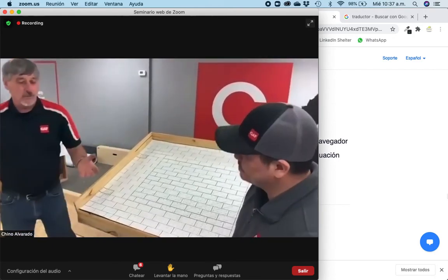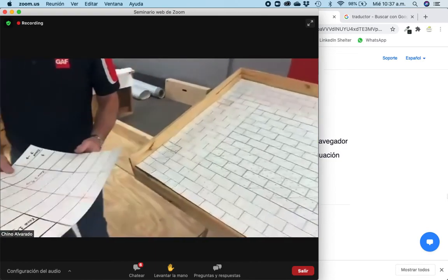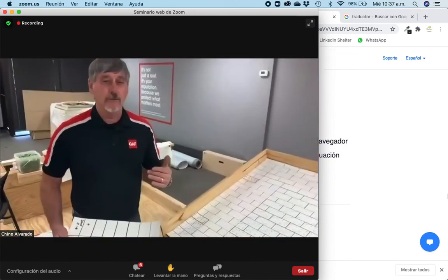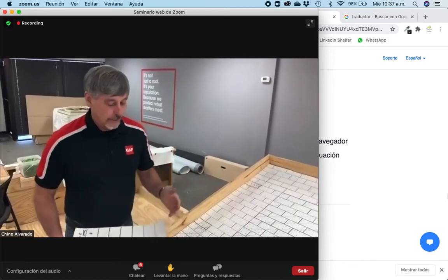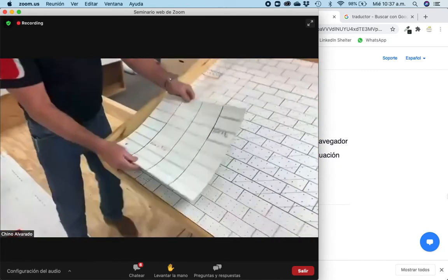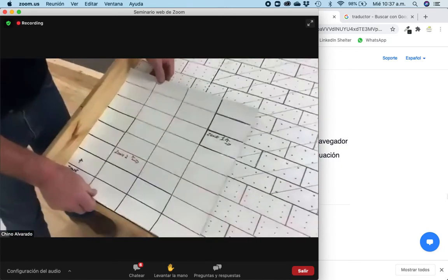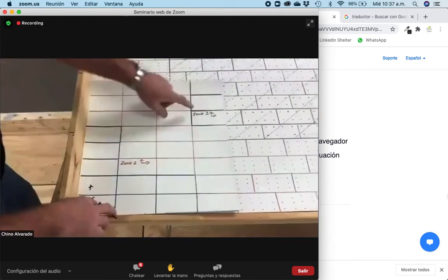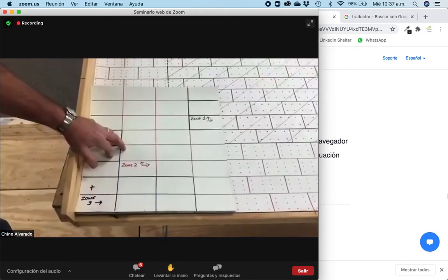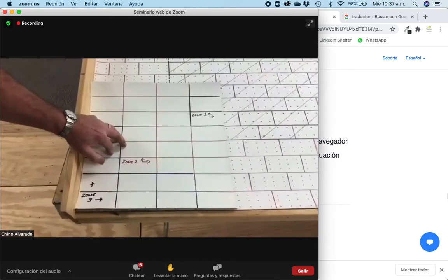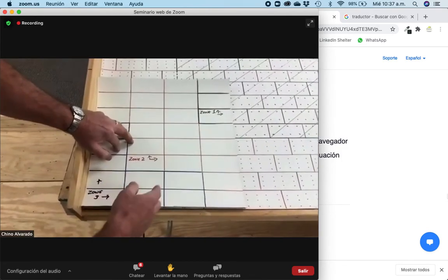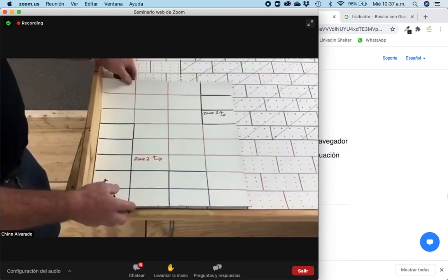But you went over. So now again, guys, I kind of drew this up. Again, this is an alternative for you installers out there. I didn't put the fasteners in here, but this is the scale. Let's say this is my corner. Here's zone 3, zone 2, and the rest is zone 1. So again, we only needed a 20-foot long corner, right? So you're thinking, well, this is adhered. Where's your stagger?